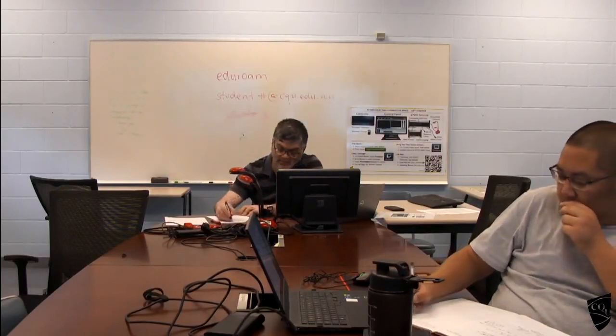You can see the cube goes to the d, which is perpendicular to the axis. So here this is the axis, and perpendicular to that one is d, so that's why it is bd cubed. Okay, so this is the second moment of area of a rectangular section.